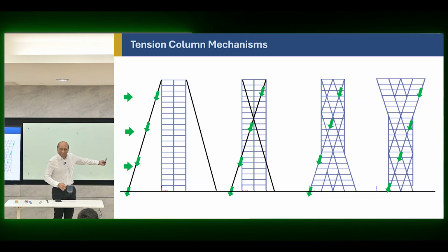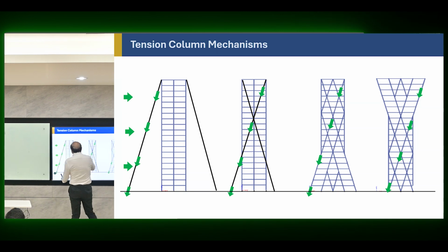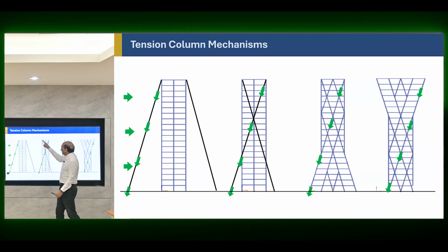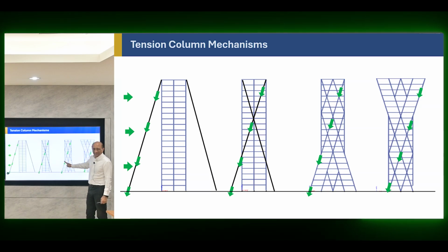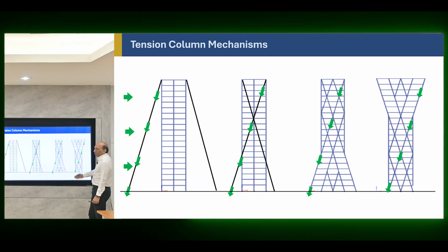The Dubai Creek Tower is exactly that, right? Somebody said, okay, why not? Let's do that. But most often you will not do it, because the space is not available. So they say, why don't we tie it like this, with one rather than two? You can move this tie here, same effect, and you reduce the base over there. Then somebody said, okay, why don't I just convert those ties into structural framing, right? Because it's a column, I can't have cables there. This form comes up, and then people do all kinds of imaging.